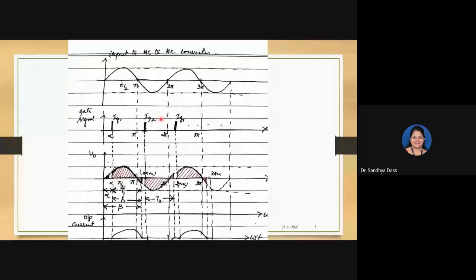So imagine if you have turned on somewhere here, alpha is equal to 90 degrees or pi by 2, so you would have got the output from here to here. If you calculate the RMS voltage from here, compared to from here, the total area, what you can see here for alpha equal to pi, then obviously it would be different. So if alpha is equal to pi by 2, then the area you can see here will be less compared to what you can see here.